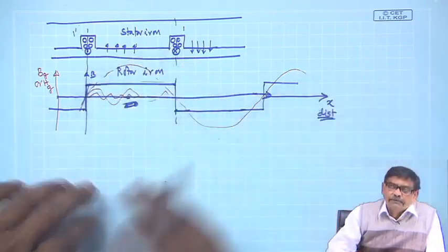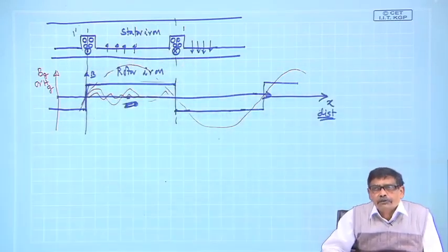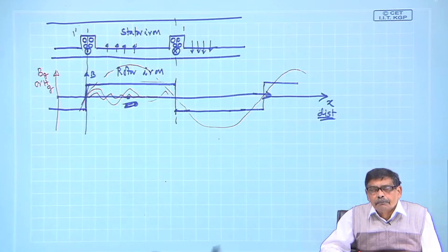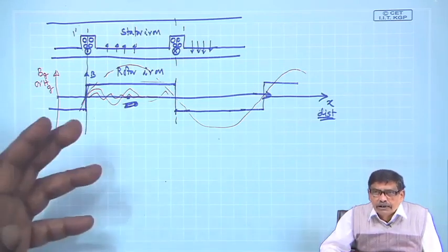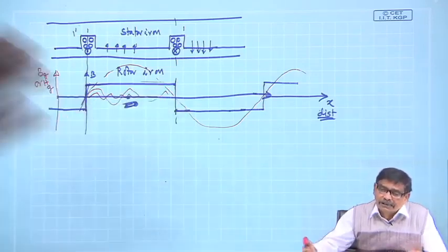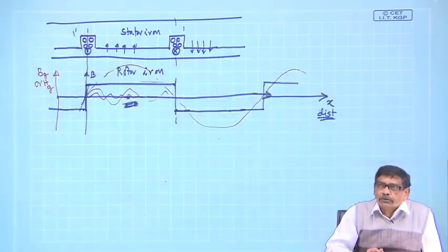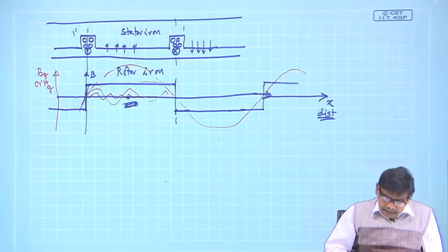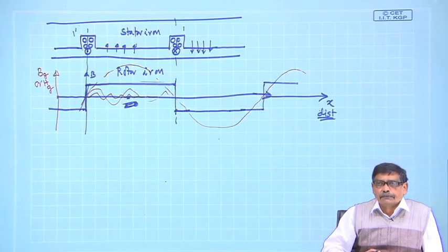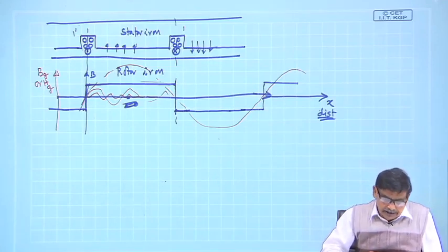For the fundamental you find out the impedance, root over R square plus omega square L square. For third harmonic, the impedance will be root over R square plus 3 omega L whole square and so on, and for each of them you will get sinusoidal terms and add them up to get the total current. But the target is to get a very strong fundamental sine wave, that is to be done. Now, how can this be done?